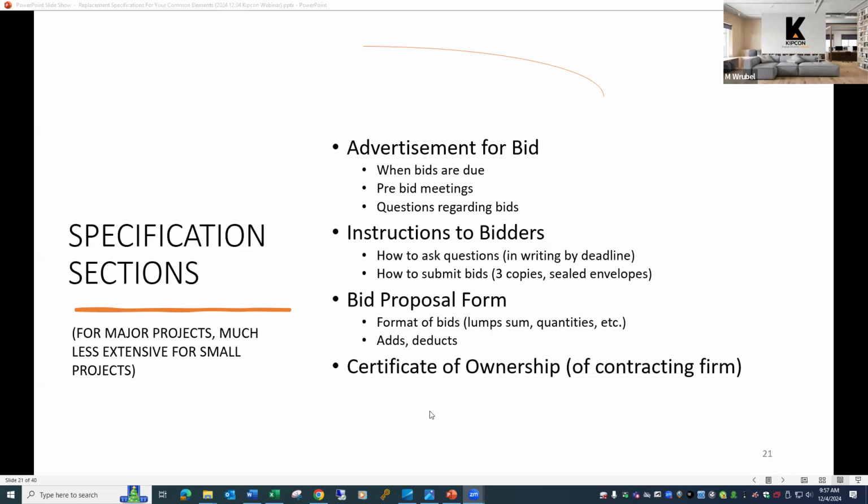And then there are extra sections to the bid form that are for unit prices. These are for items that may be needed or typically needed during a certain type of project, but may not be needed, and it'll become apparent once construction begins. And I had already given the example of pavement in terms of any kind of base course repairs. Say in a roofing project, it might be some rotted sheathing that's uncovered once the old shingles are taken off. And that might go into the unit price section. You don't know for sure you're going to need to do that during the project.